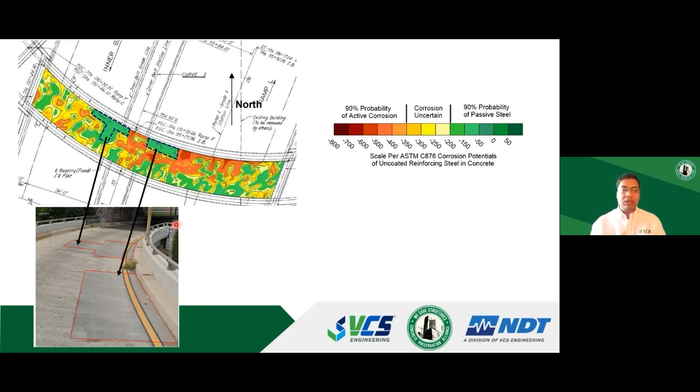And that's what you see in the corrosion potential measurements. Whereas right outside these patch repair areas, that's where you see active corrosion happening, because you would still have chloride contaminated concrete right outside the patch repair areas. Essentially, this effect is called the ring anode effect or incipient anode formation, and we can talk about that later.